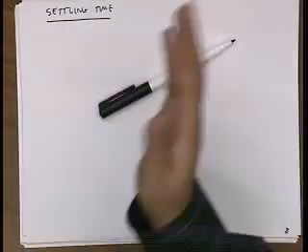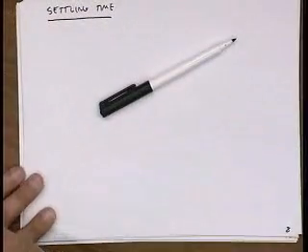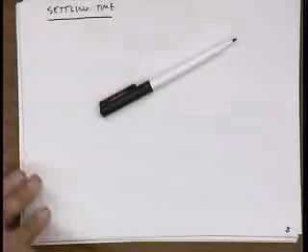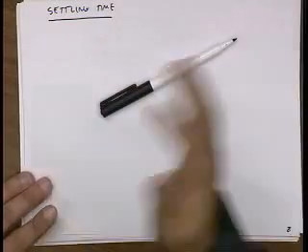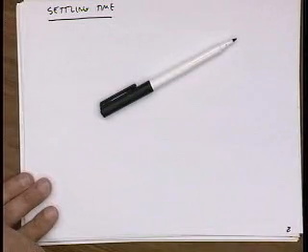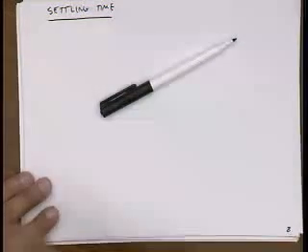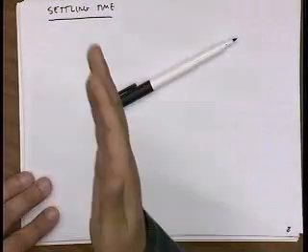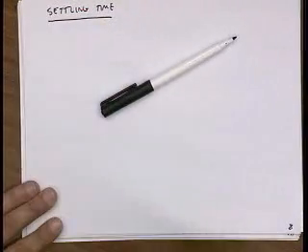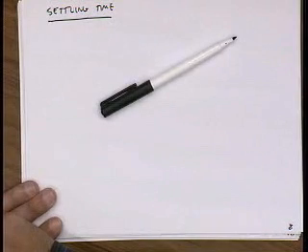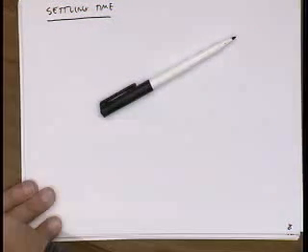So let's say I'm doing digital signal processing, and the resolution is 10 bits, right? So that means the smallest number is 1 part per thousand, 1 over 1024, if you want to be exact. So if my circuit settles within that accuracy, right, of the quantization noise of that converter, then I really don't care.